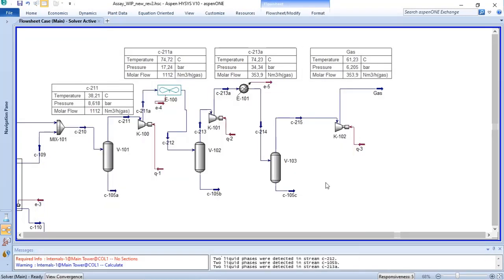And there is a limit for the pressure ratio, because once you compress the gas too much, its temperature goes up, and to not damage the equipment, the suppliers and manufacturers calculate the outlet temperature, which goes around 150 or something like that, to protect the materials used.